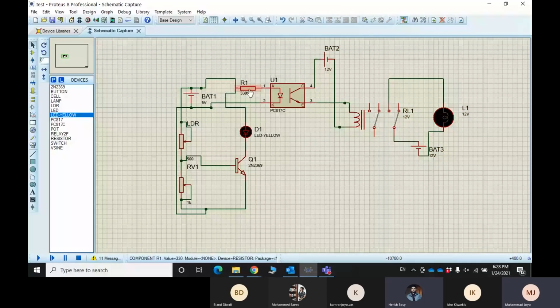Okay, now this is the pin available to you. Now I want you to attach this whole circuit to this transistor. So when there is light, it will turn on this lamp. When there is no light and the resistance increases to 50K, this relay will be switched off.